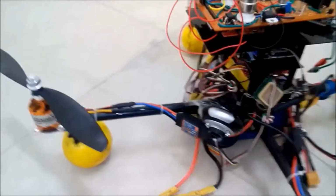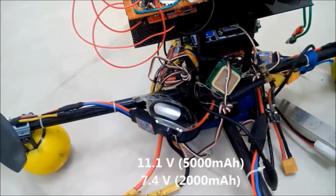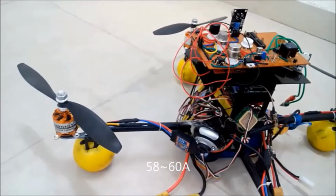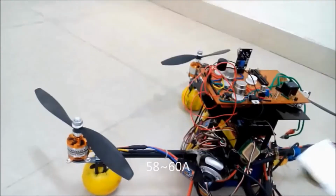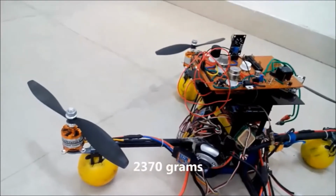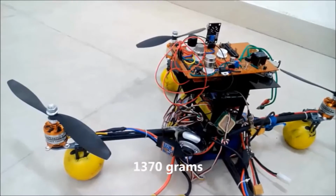Power to the quadcopter is given by two lithium-ion batteries of 11.1 volt 5000 mAh and 7.4 volt 2000 mAh. The whole quadcopter draws about 58 amperes of current, and these two batteries are capable of running this quadcopter for about 30 to 35 minutes. The whole quadcopter weighs about 2370 grams. So we have used 4 BLDC motors, each of 1370 grams of thrust.